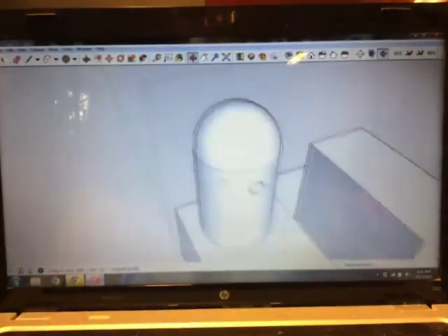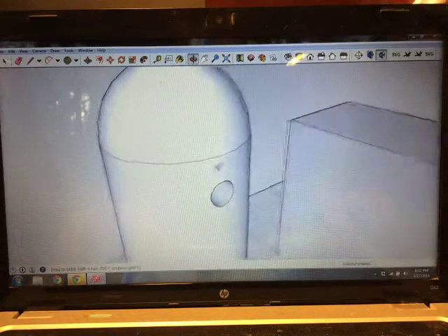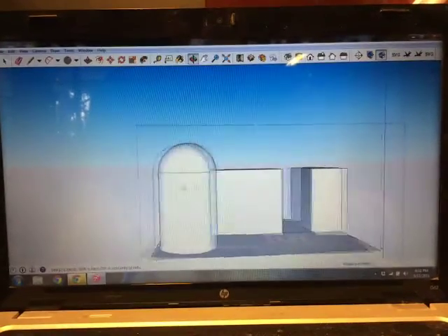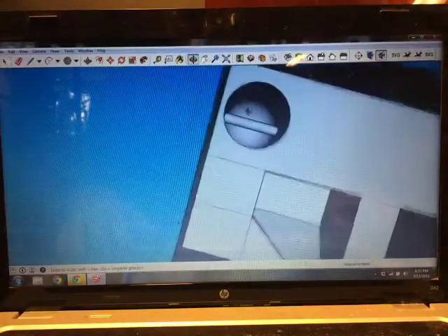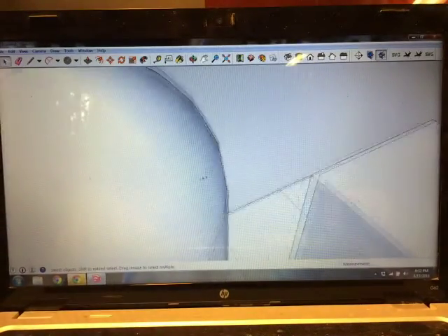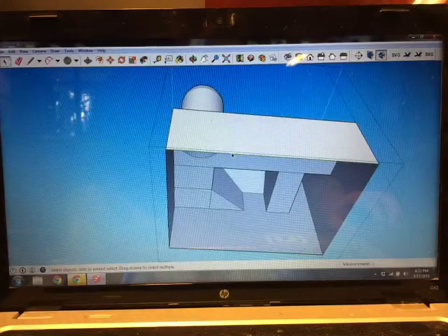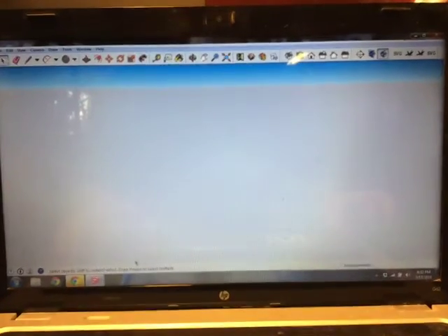If the item is too small, like less than a millimeter, then it has rendering issues. So let's jump up here, and sometimes it will delete the face. I think it has. So I'm just coming up out of the dome. It looked like it deleted the flat face that was on top of this. Yeah, it did.